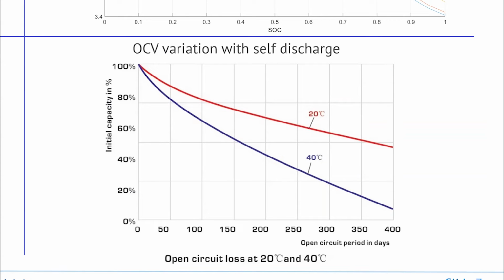It's very evident in this graph, blue versus red line. Another factor that comes into play is your SOC, state of charge. State of charge is a very important factor, and it will influence the rate at which the cell starts to degrade. For example, if I store at very high SOC values, say greater than 90%, this will cause fast degradation. There will be very fast loss in voltage, loss in capacity, things like that. But if I store at near 45 to 55%, it is optimal.